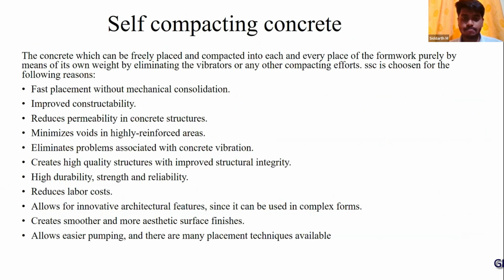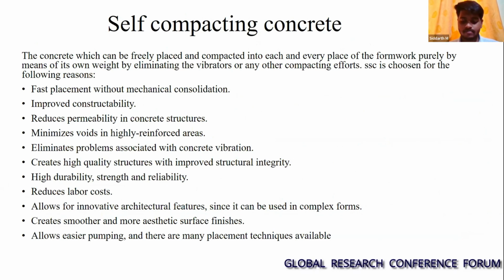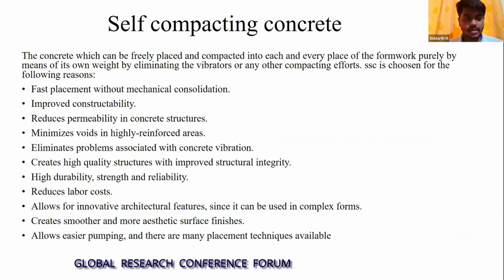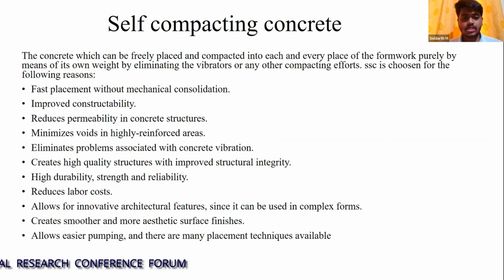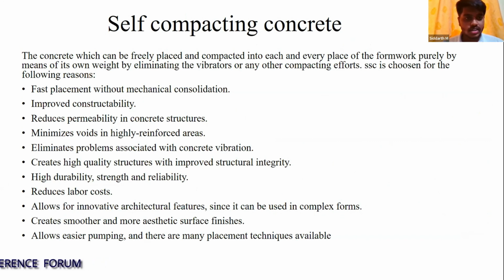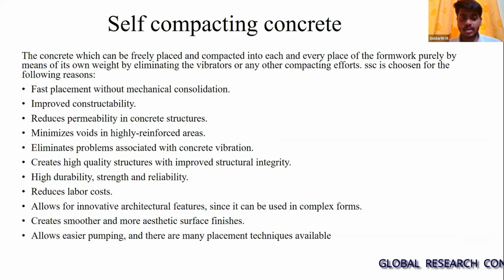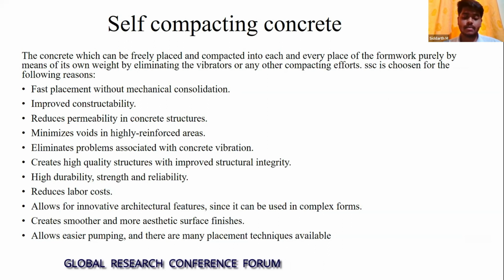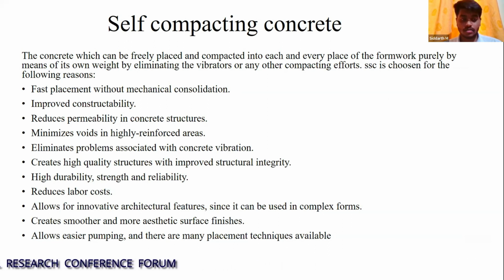We in our project have included self-compacting concrete. So let's see about self-compacting concrete. It is the concrete which can be easily and freely placed and compacted into every place of the formwork by means of its own weight, eliminating the vibrators or any other compacting efforts.